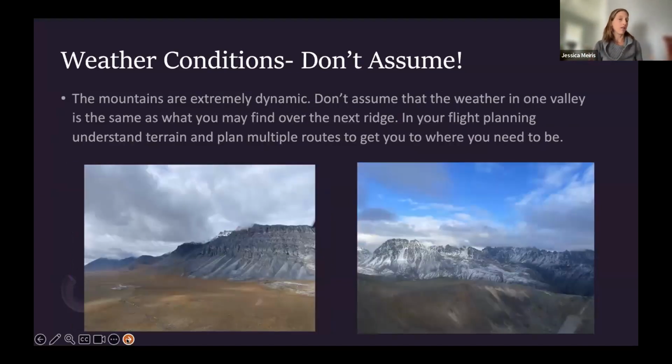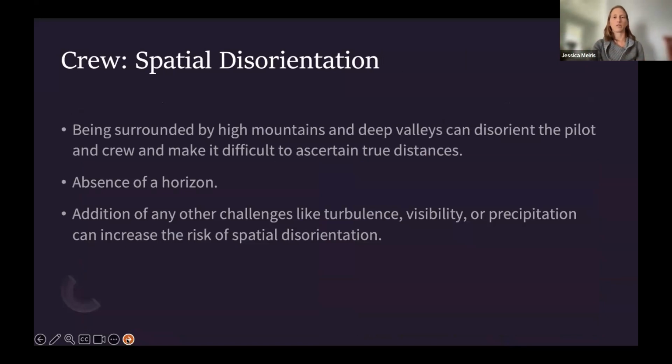Don't ever assume that conditions in one area are going to be the same in the next valley over. So, hey, looks nice, VFR conditions, and then you cross this low point, cross the saddle, and all of a sudden it's a very different environment on the other side. And along those same lines, always have different options when you're in a valley, and take that same mindset when crossing from one area to another. Always understand where you are, maintaining situational awareness, and have a few different escape options to get out from your current position.